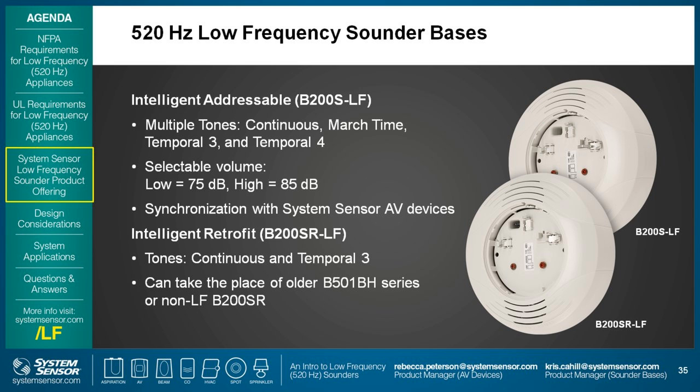The B200S-LF can generate continuous, march time, temp 3, and temp 4 patterns. The temp 4 is important since this is the tone you need for carbon monoxide applications. High and low volume are selectable. Another important feature is that they can synchronize with other System Sensor AV devices.